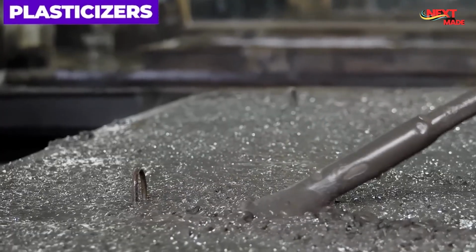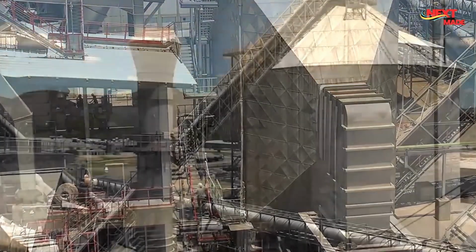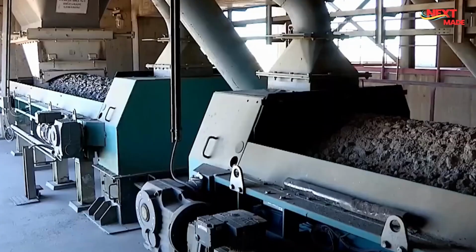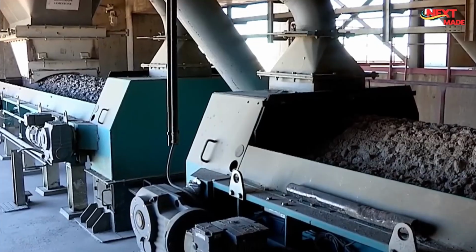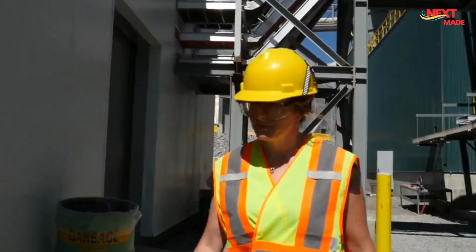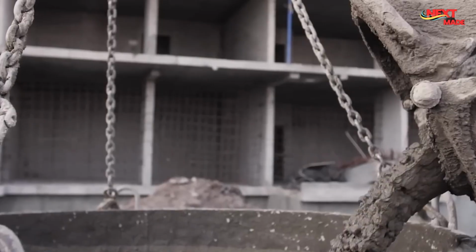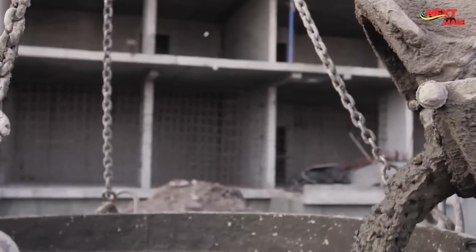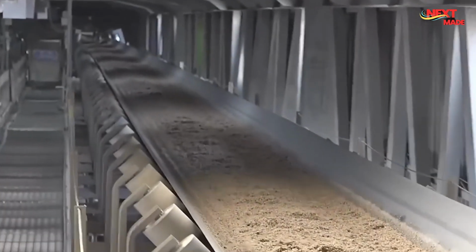With the raw materials all there, concrete production can finally begin. The first step is to measure the proportions of cement, aggregate, admixtures, and water based on the desired strength and characteristics of the concrete. In fact, concrete mix design is an entirely different discipline dedicated to finding out the right proportions of raw materials in order to reach a target tensile strength. Moreover, building codes have been developed that specify the ratio of cement, aggregate, and water based on the different types of construction. The next step is to mix the ingredients thoroughly to create a uniform mixture.